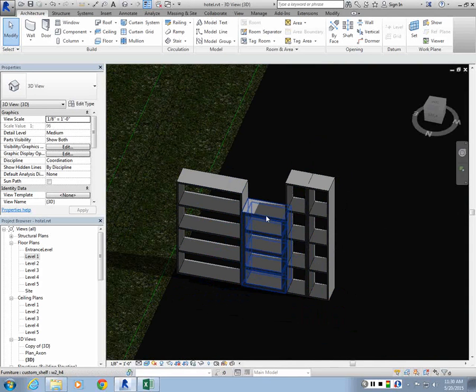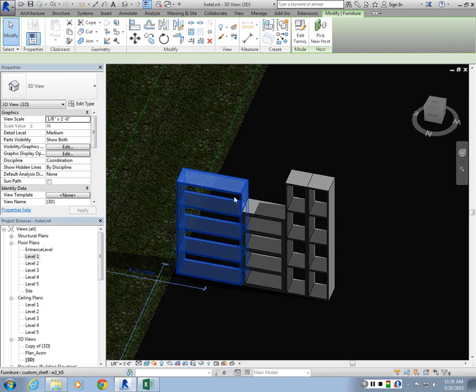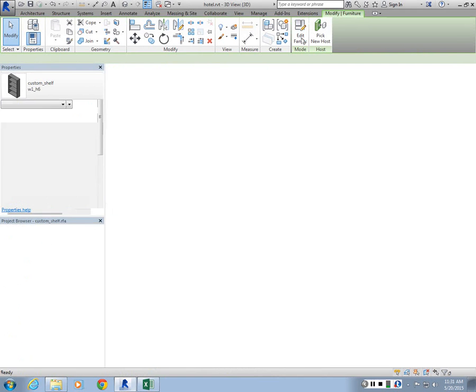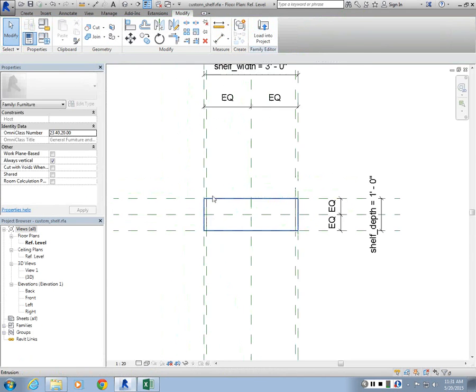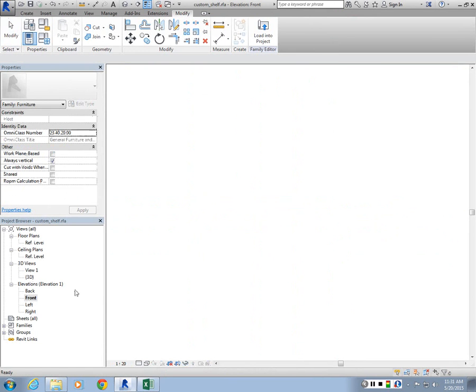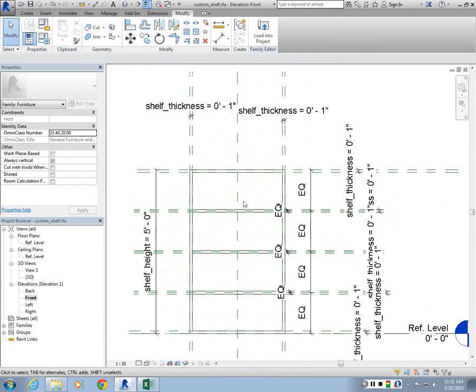Now this is actually half of what we can do with families. Even if you create these, you can still update them, you can still modify them. So I can choose this family here, any of the instances, and I can do edit family, and it will take me to the family window that we had. So let's go there, and let's do some more stuff. So I'm going to go to my front elevation, and I'm going to create some panels here. So let's look into that.